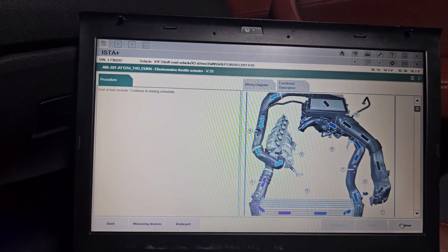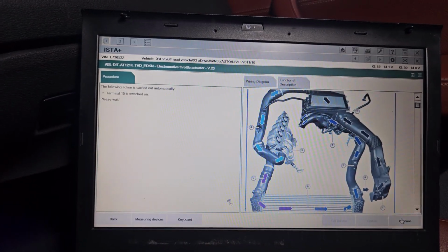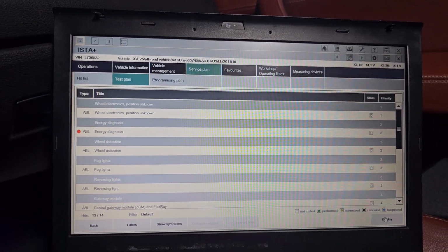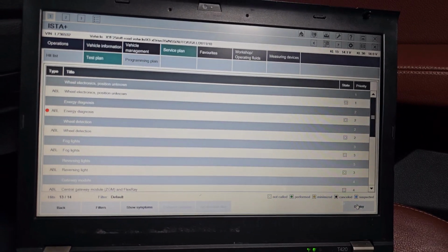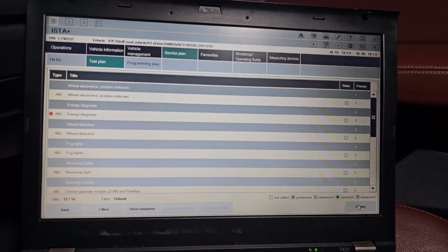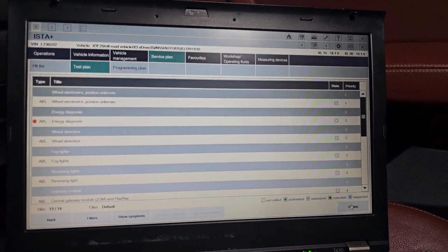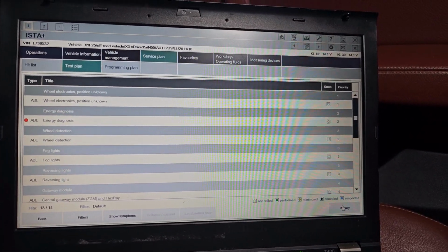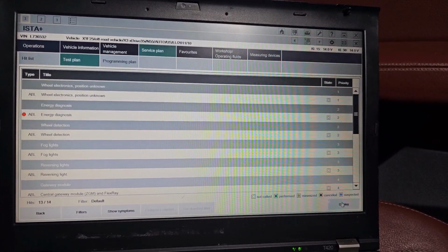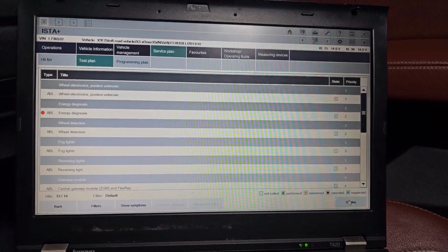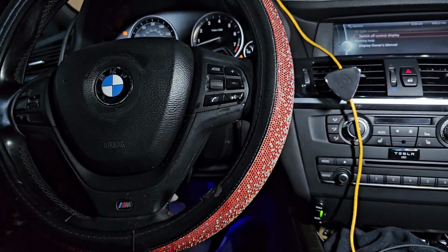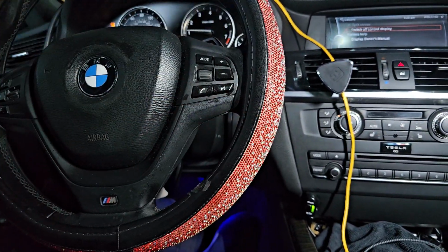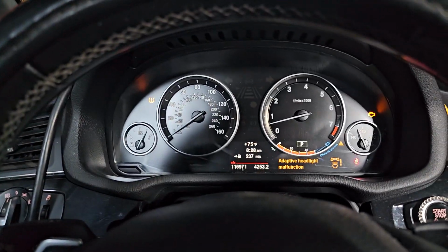Okay, so we know that we have something inside the intake manifold or the crankcase. There is a leak somewhere that is creating this problem. Maybe we have to start with a smoke machine, but most of the time it could be the crankcase ventilation, or could be the PCV valve. It could be anything that is not the throttle body itself.